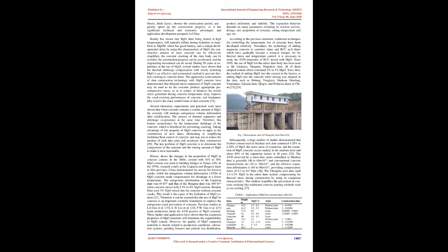18. Several laboratory experiments and practical work have shown that when concrete contains a certain amount of MgO, the concrete will undergo autogenous volume deformation after solidification. The process of thermal expansion and shrinkage occurs at the same time. Therefore, this feature compensates for the temperature shrinkage of the concrete, which is beneficial for preventing cracking.